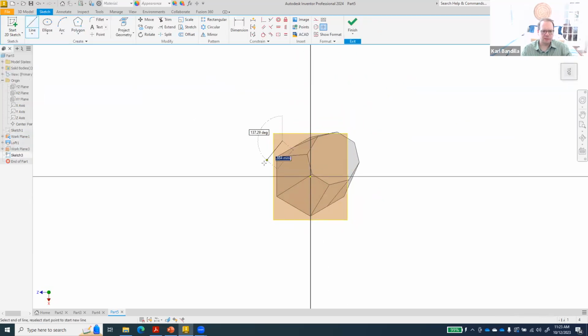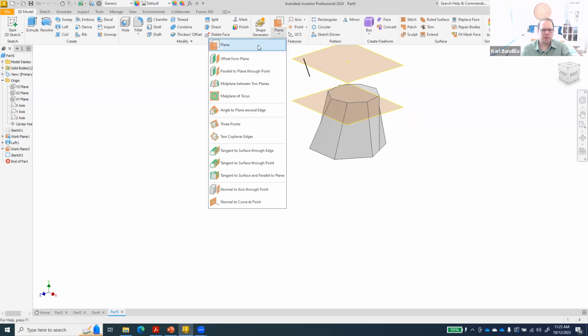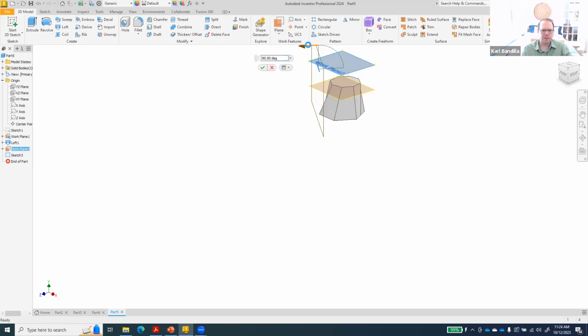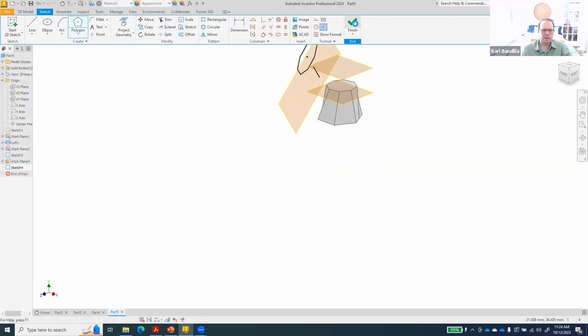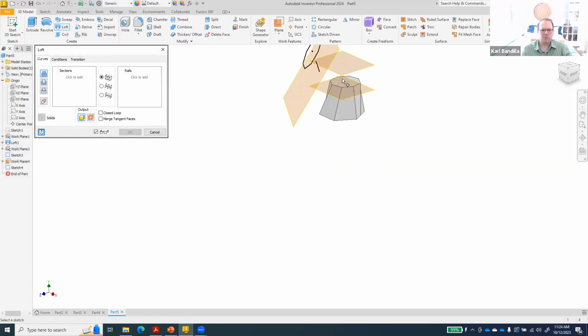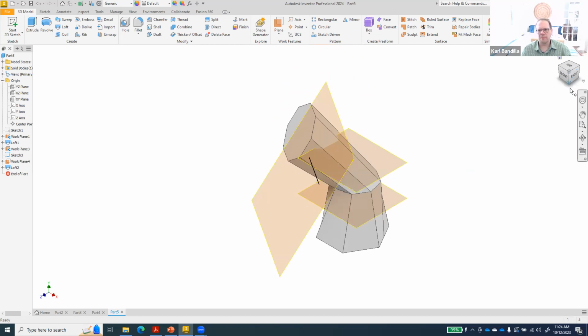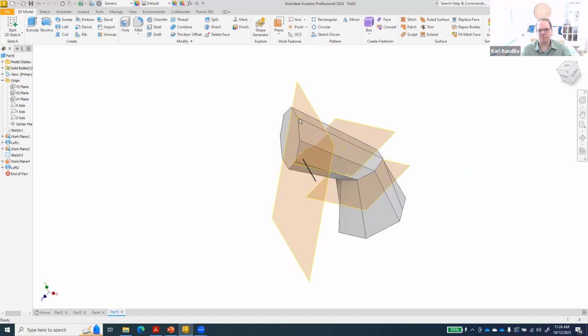And we'll just draw a line on this one. Not a spline, but a straight line, doesn't matter where. And then we want to have a plane that is at an angle, like this one, angled around there, and choose whatever angle, doesn't matter. And now we can draw on this one. Do it there. And then do another loft. All right, go from this shape to that shape. And there you go. Zoom in. Looks a little bit like a telescope. Not really. Right, but you can create some pretty cool shapes with this stuff.